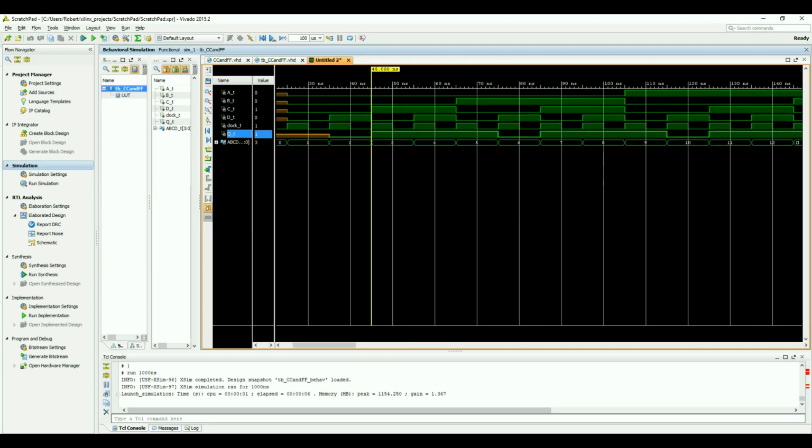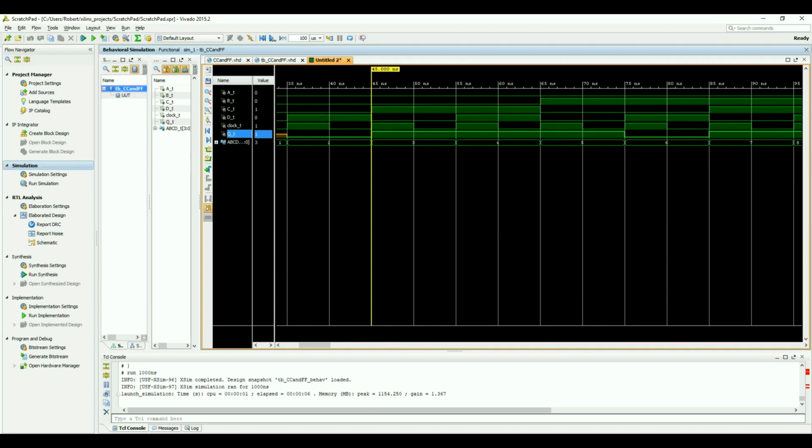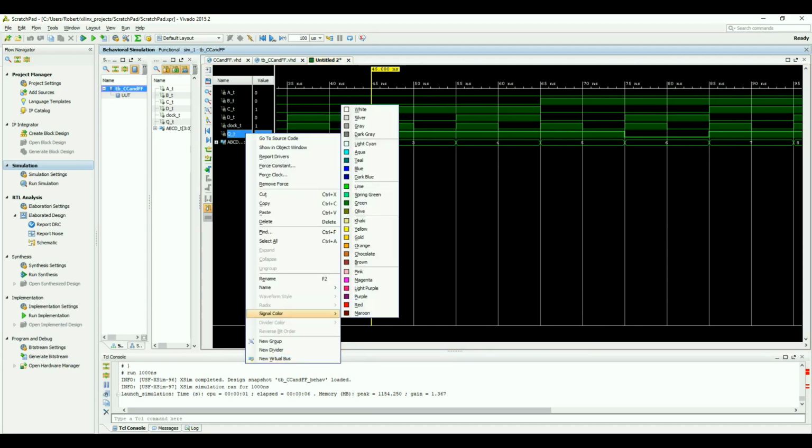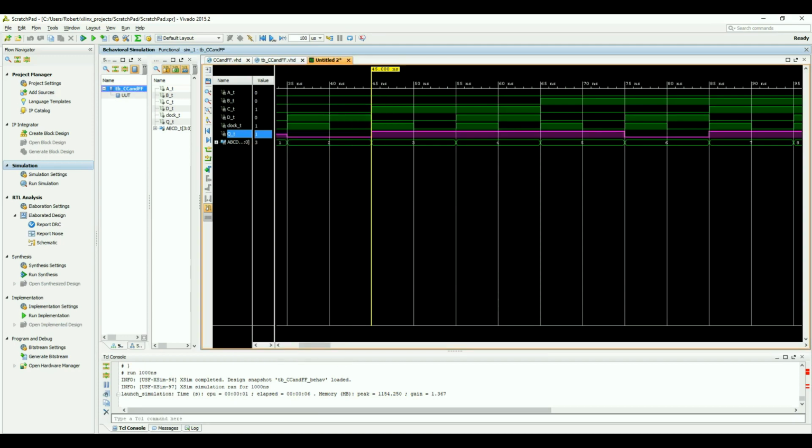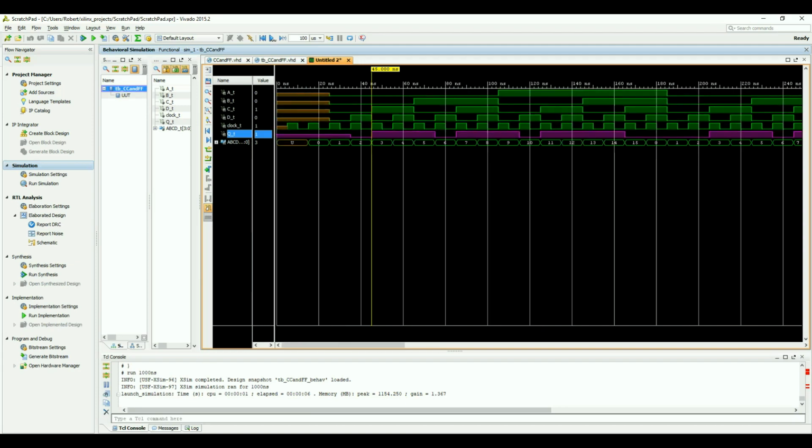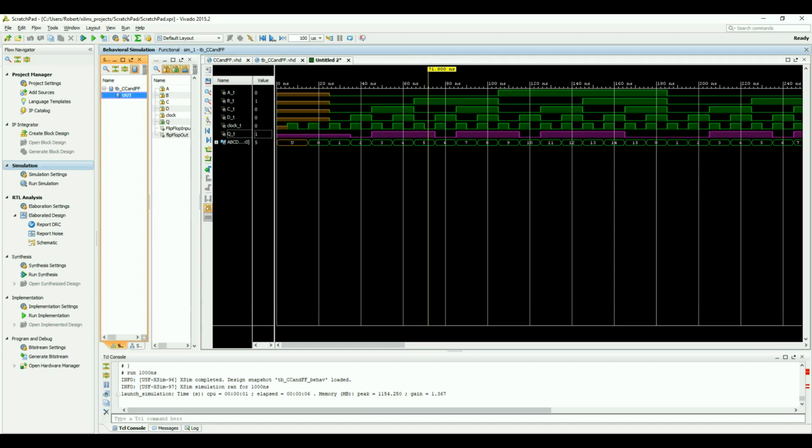If you have multiple flip-flops, things start to increase in complexity. For exhaustive testing, you would have to drive one flip-flop high, perhaps the other one low, say they were cascaded, and then you'd run through every possible combination, and then you would repeat the test with maybe the first one being high and the second one being low, and then you would repeat the test again with both of the flip-flops high, and you might repeat the entire test again with both of the flip-flops low.